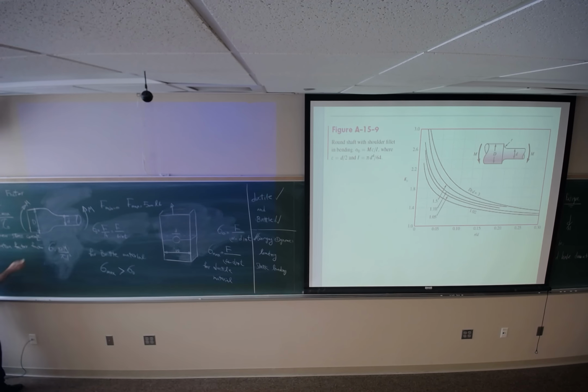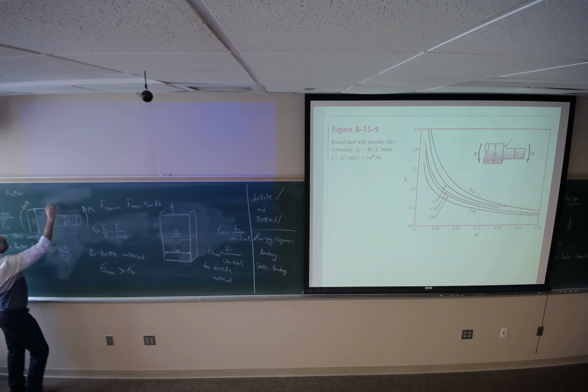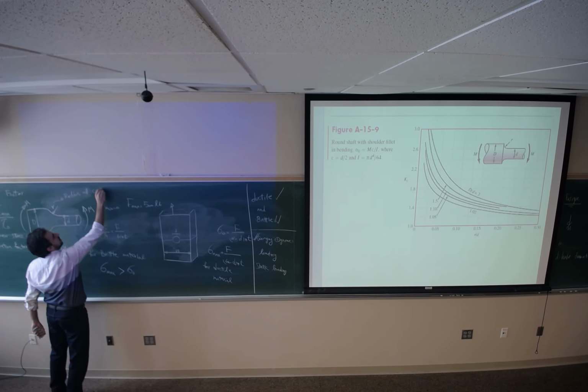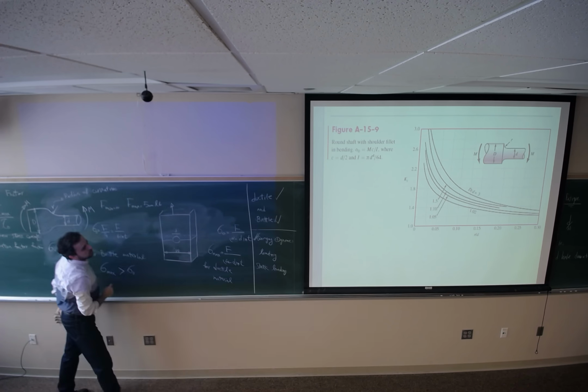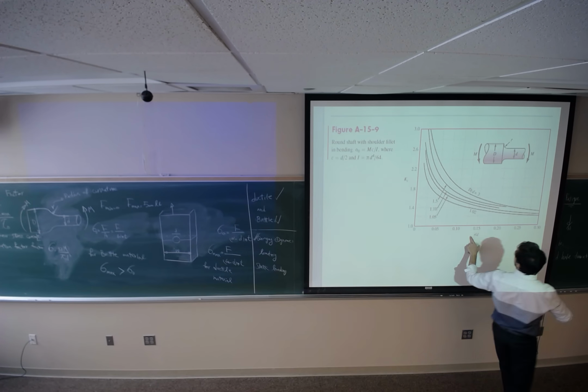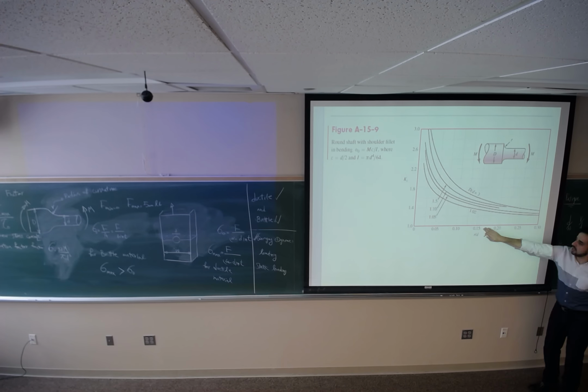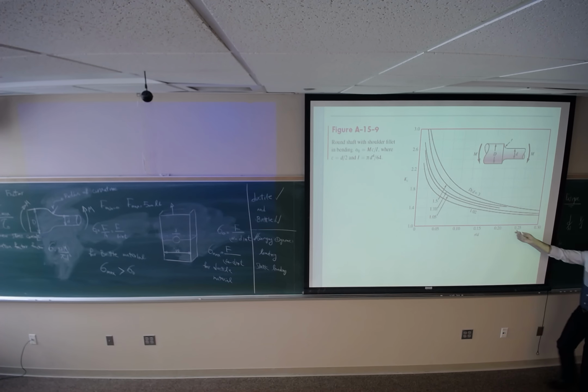But due to the discontinuity that I have in this shaft, because we have this cross section which has been shrunk to the smaller size, this curvature has a radius. So we call it r, or radius of curvature. You can measure it, or you are given that radius, and you divide it by the smaller diameter, which is d, and you read the number. Suppose we are here, 0.2.